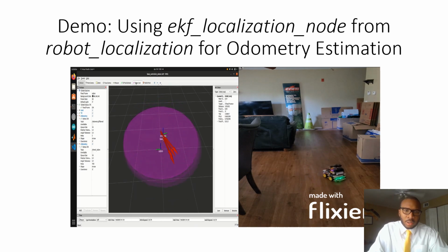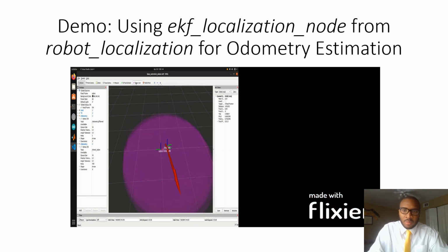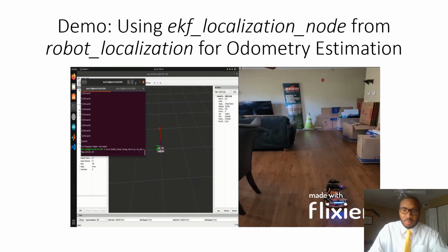And I know you all noticed a purple circle around the state estimate, and essentially what that represents is the pose covariance that is growing without bound. The reason it's growing without bound is because there is no global state estimate, such as something from a GPS or something of that nature, being fused into the extended Kalman filter algorithm to converge the pose estimate. Because of that, that's something else that I can improve in the design of the robot moving forward.